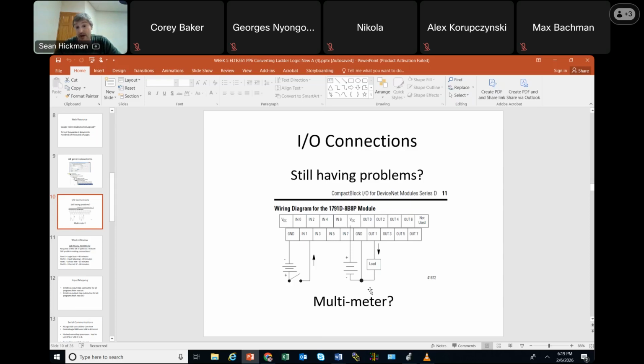Really, what you got to do is unhook all the devices, let the DC power supply reset, cycle the power on it, and then boom, the DC comes back on, and then you can try it again. But if you hook this all up again and just do a dead short to DC to ground, you're just going to trip it again. Okay, so